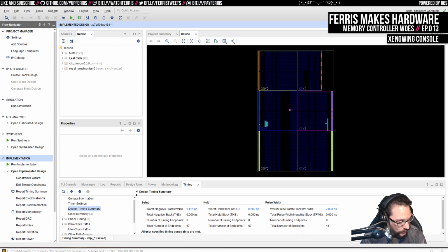I removed the DDR controller, and I replaced all of that memory with block RAM, which is inside the chip itself. And the nice thing about that is that then it's very clear if my design doesn't meet timing. It should also be a lot easier to constrain the design and make the tools handle that properly. And in that case, I did actually still have some timing issues that finally appeared in my design, running at 150 megahertz. And I think a lot of those actually came up as a result of switching to block memory, because I think that has to be distributed around the chip now. So I think there are some constraints that made that a little bit different.